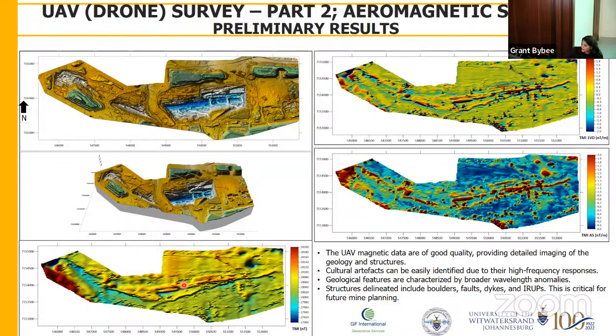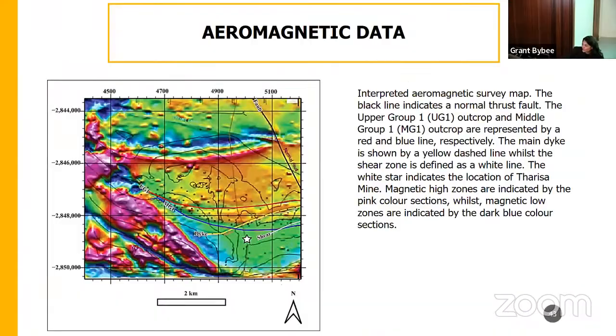So this is our TMI map. What our TMI map was able to do was see areas of higher magnetic intensity compared to areas of lower magnetic intensity. The features were not that enhanced. So what we did is applied a first vertical derivative filter to our data, and we can see that the features are more enhanced. So you can see now that there's clearly distinct lineaments as compared to our previous data, where it's not too clear of where the lineaments associated with the actual mine are.